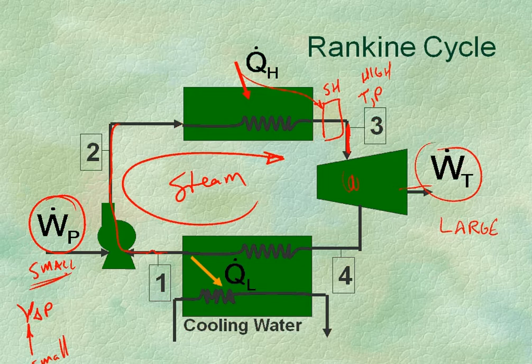Now in the Rankine cycle we do reuse the working fluid, mainly because these liquids that we use are usually treated with anti-corrosive agents and different things that make them suitable for running through this heat exchanger. You want to make sure you have low corrosion in your heat exchangers, and so you'll treat your water. That's kind of expensive, so you want to reuse that water.